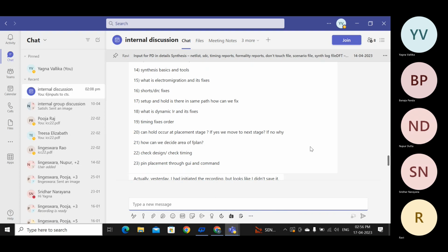Tools, as I said, synthesis tools. If it's Synopsys, there is DC for logic, DCT for physical aware, DCT SPG for physical aware with floor plan information. If you want IBM tools, you can talk about BuildGates. If you want Cadence tools, you can talk about Genus, and RTL Compiler, right? So those are the tools. TCG is again, congestion aware synthesis.